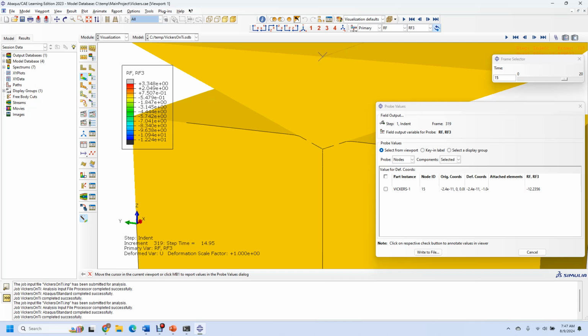Unfortunately, these are vastly off from what we expect in the real world, and I attribute that to, for a three-dimensional model, our meshing probably not being as small as we need to actually measure the effect of the stress field and the resulting deformation. So I think meshing could be improved, and with a student license I'm limited to 1,000 elements or 1,000 nodes.